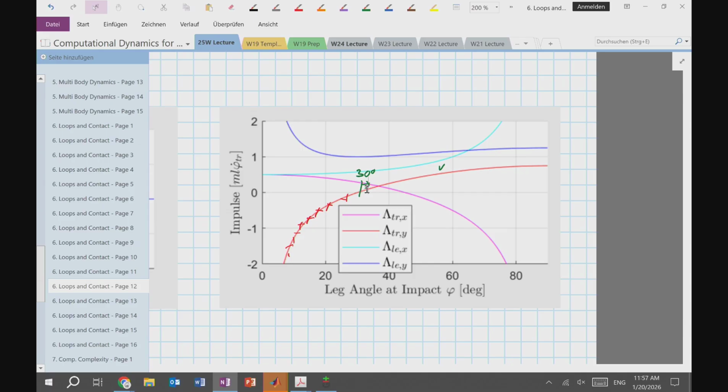If I draw an arrow like this, it has a normal force of 0 and some finite tangential force, and the ratio of these two, of course, is infinite. That's what mu equals infinity means. This would be your friction cone for some finite mu, and then if you increase your mu, it gets larger and larger, and for mu equals infinity, you get both directions, plus minus 90 degrees.